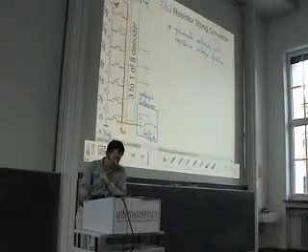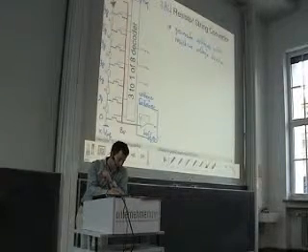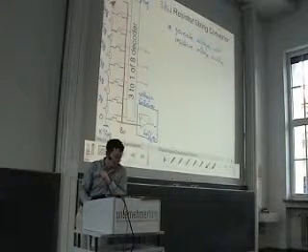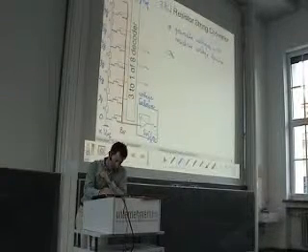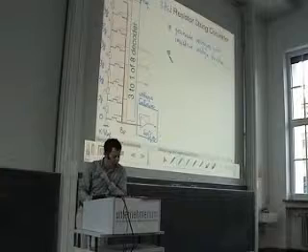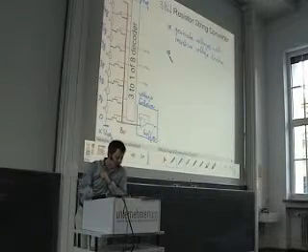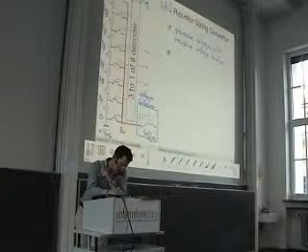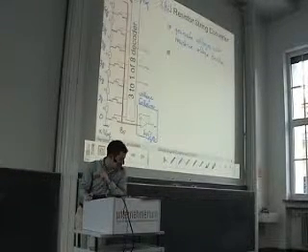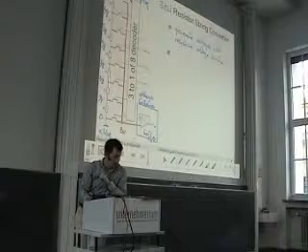So the highest voltage that can occur is at this node. So we have the situation that the max voltage is 7/8 Vref. The control voltage at the gate here is the highest voltage we can use here. So it's, let's call it VDD.